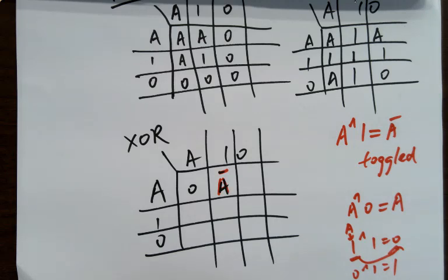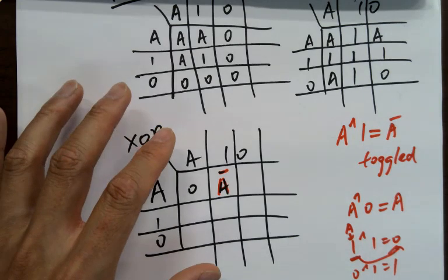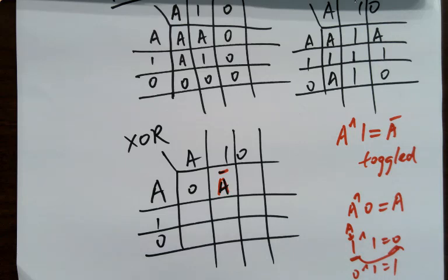So logic 1 in a 5 volts logic, what kind of voltage is it? If, for example, I grab the board you are looking at, the microcontroller, Arduinos are 5 volts, okay? The PIC we are using is probably 3.3 volts, I forgot. So the logic 1 for the whole digital system will be the power supply. For Arduinos, logic 1 will be 5 volts. For the PIC, if it's a 3.3 volts power supply, logic 1 will be 3.3 volts. They are both logic 1.